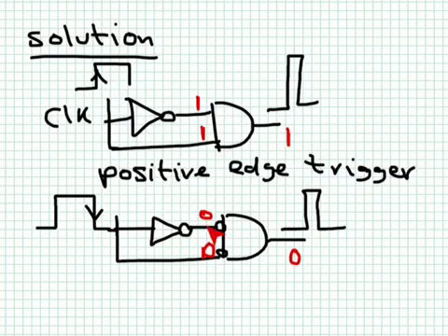So there will be a very short duration of time where both inputs to this inverted AND gate are zeros. So when you have 0 and 0 here, they are inverted to become 1 and 1, and then you get this very narrow short pulse. After this short duration of time, this input here becomes 1 again, so you end up getting 0 again at the output. So this circuit I explained creates a very short pulse corresponding to a rising edge, while this one creates a very short pulse corresponding to a falling edge.